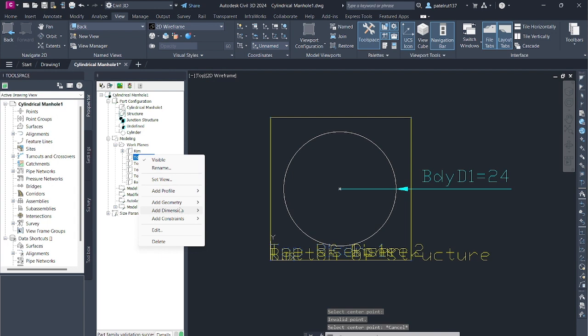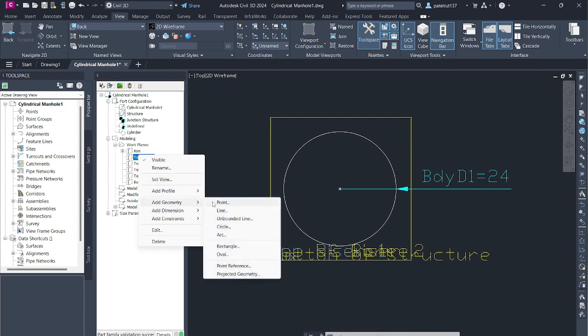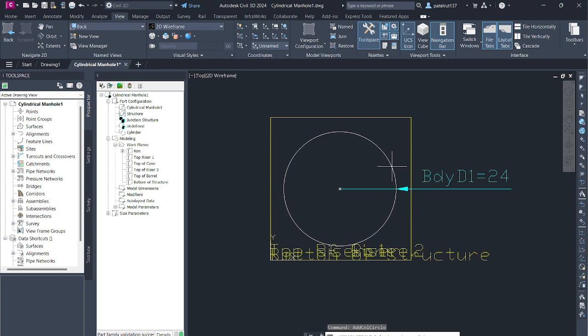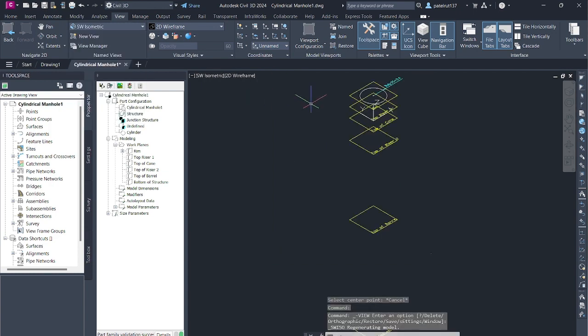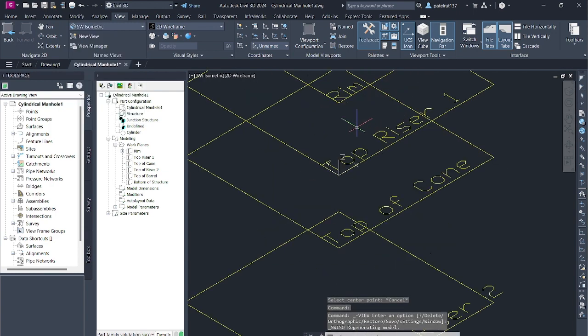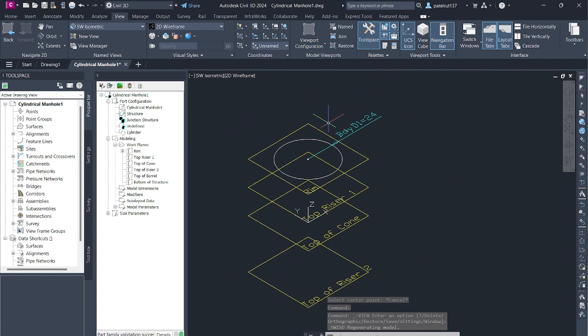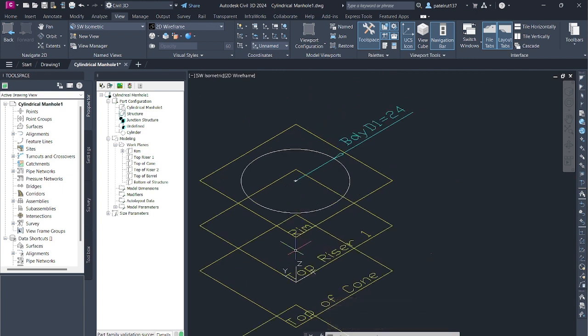Repeat steps 16 and 17 for SRZ1 and SBH, adding the following values to each list. SRZ1 equals 12, 24, 36, 48, 60. SBH equals 100, 120, 140, 180. Click OK to exit the Edit Part Sizes dialog box. Lists of values are now available for SRZ1 and SBH.